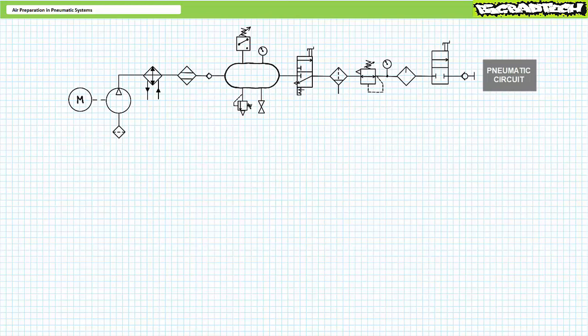Additionally, consider simple operator error. What if the shutoff valve on the left of the FRL was mistakenly placed in the bottom position during normal operation? Would actuators in the circuit work as intended? Absolutely not. Placing this valve in the bottom position prevents passage from left to right and vents everything upstream to atmosphere. Both valves must allow passage from the receiver to the FRL and from the FRL to the circuit for the circuit to run. Lastly, consider erroneous system setup.